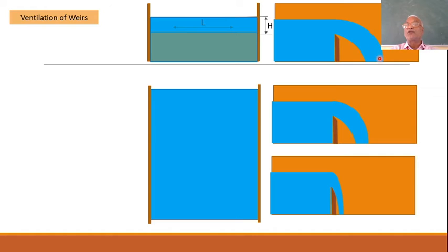Now when the flow continues, some of the air goes along with this sheet, so for this free nappe which is flowing like that, because the air is gone, there will be suction pressure. This nappe is dragged inside, more air goes, and this nappe is forced to cling to the weir wall itself. Such a condition is known as a clinging nappe, or sucked nappe, while this is a free nappe. Here when it is flowing like this, there is a suction pressure, more water is discharged, and the discharge will not be the same as that proved theoretically.